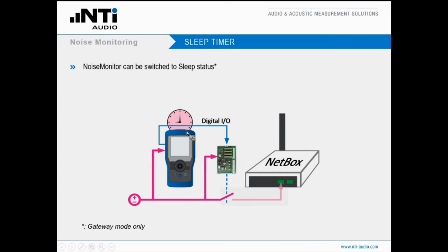Well, this setup allows us to switch off the netbox through that PCB at a certain time. We can program the XL2 in a way that it switches off the netbox from the power supply, and it also itself goes into a sleep mode. Internally, the real-time clock is continuing to work, and this real-time clock will also wake up the system, but in this status shown here, we have minimum power consumption of our noise monitor.